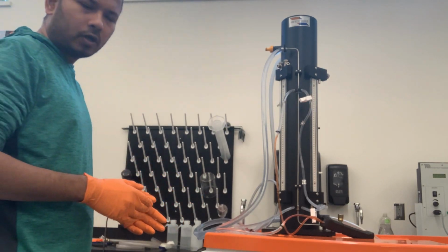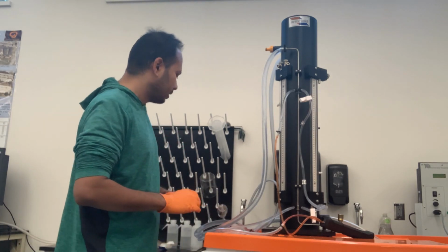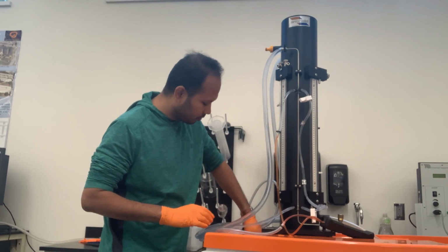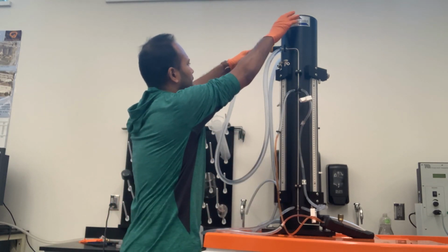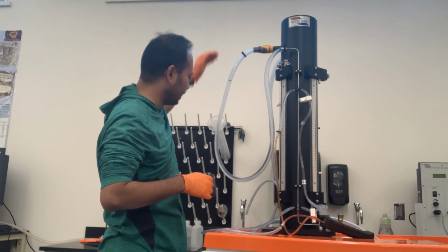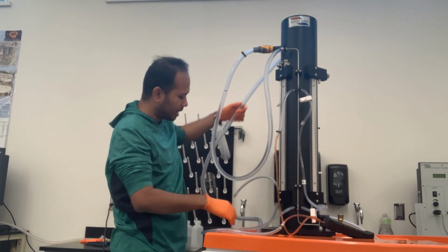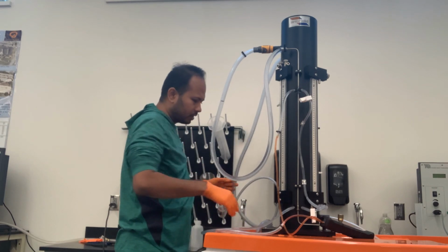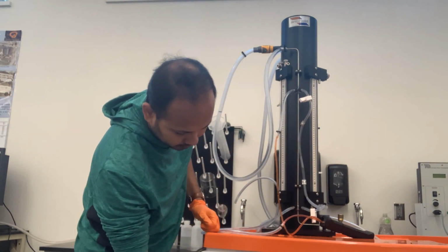So for the low flow rate, I have to turn off the pump. Remember, you have to change the inlet of the water to the outlet of the tank here, the constant head tank. Now I need to feed the tank, so this pipe has to go into the inlet of the pump, and I can run the test.